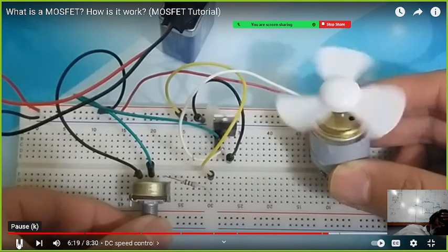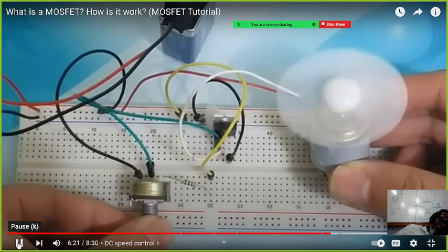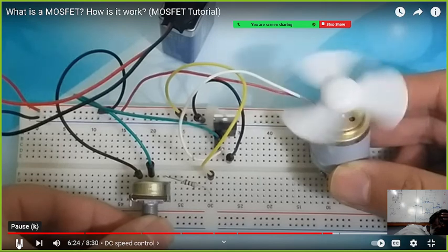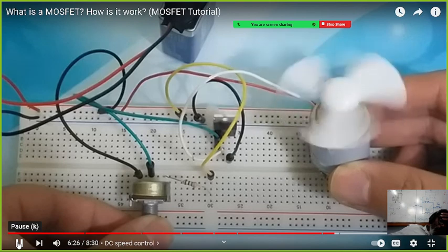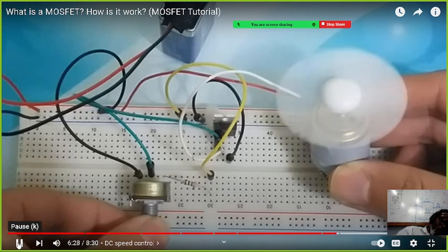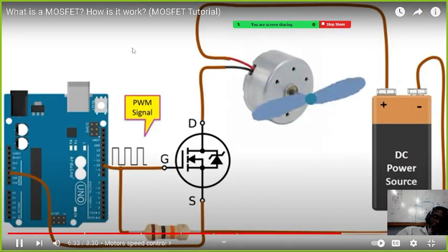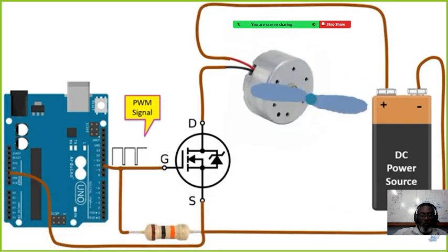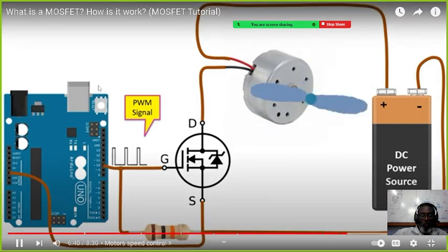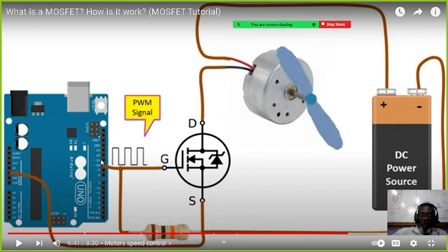With a 9-volt battery, we can control the speed of a small DC motor with a potentiometer thanks to the MOSFET in this way. As here, the working principle of systems with big electric motor fans is the same. With MOSFET, we can control the speed of a motor not only with a potentiometer, but also with a microcontroller, as here. Since the right, I can use a computer, because the computer uses a microprocessor, which is the CPU, and we do it through the parallel port.